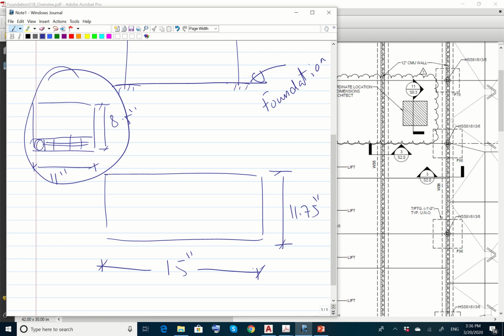So how can you tackle this? You need to create a new layout with those dimensions. There are some standard paper sizes, so actually you double those numbers. The one you're going to be using is 22 by 17 inches. So 22 by 17 will fit your drawing when it's plotted with a scale of 1/8 of an inch equal to 1 foot. So you're going to be creating a new layout. Don't use the layout that you already created.